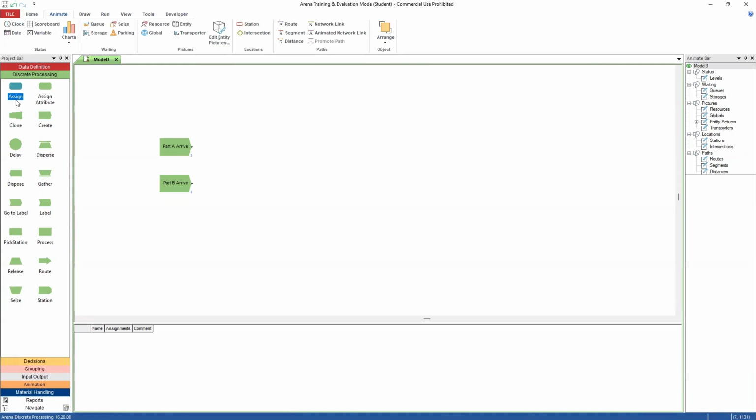We have different processing times by part type at the sealer operation. So we will use two Assign modules to define an attribute called sealer time that will be assigned the appropriate sealer processing time after the parts are generated by the Create module.